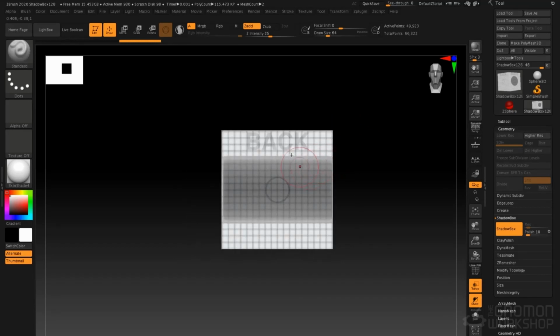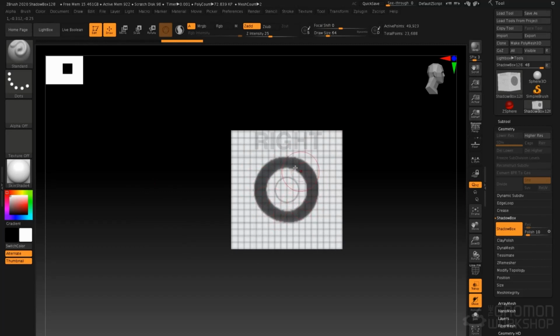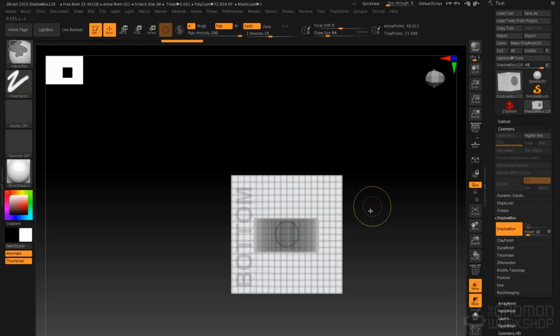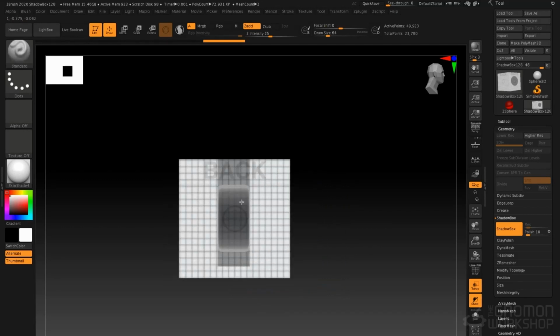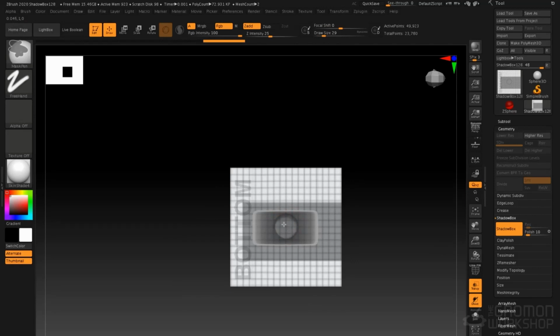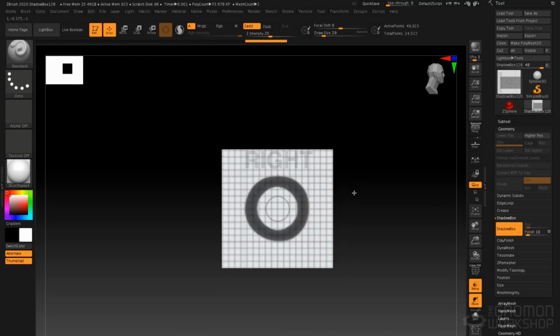If I go to the back view and then I draw a rectangular mask, it will limit the depth of that other mask. Now I've got a mask here and down here, but there's no geometry being created on the unmasked areas because this is being limited. Now if I go to the top view, and let's make another mask, again, it's bigger than the geometry that's being generated, but it's being limited by this mask here. If I come to the top view though, and then I erase out a circle here, I'll have a circle that's erased out through the geometry.